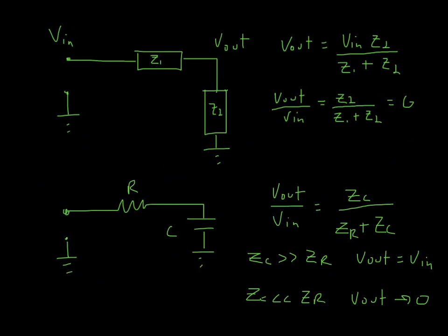And now here's the thing, when does that happen? So when C is really, really big compared to R, that would be for omega very, very small, for DC, all right? Remember, this circuit here, this impedance looks infinite at DC. So this one, the top one here, happens for omega small, all right? And this one down here, there's not a lot of room, this one happens for omega big, all right? And then I'll circle those.